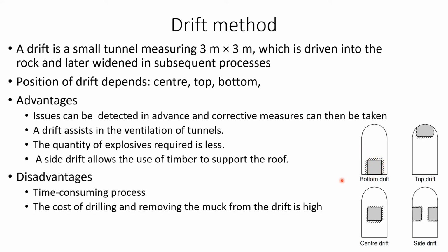If the alignment is not proper, there can be a chance that the two ends of the tunnel won't meet at the same point, because usually when you are doing the tunnel driving procedure, we start from two ends. For example, this is a tunnel connecting point A with point B. The driving procedure, we start from these two ends.